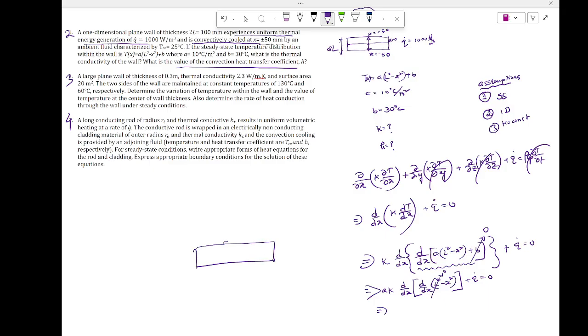If for the second part, at this surface, you want to find the conduction. Does it make sense? I should be putting this as convection. The top one is convection, okay. So this conduction, to find that at this surface, you know, at point to point it varies. You do minus k dT/dx at x equal to 50 millimeter.